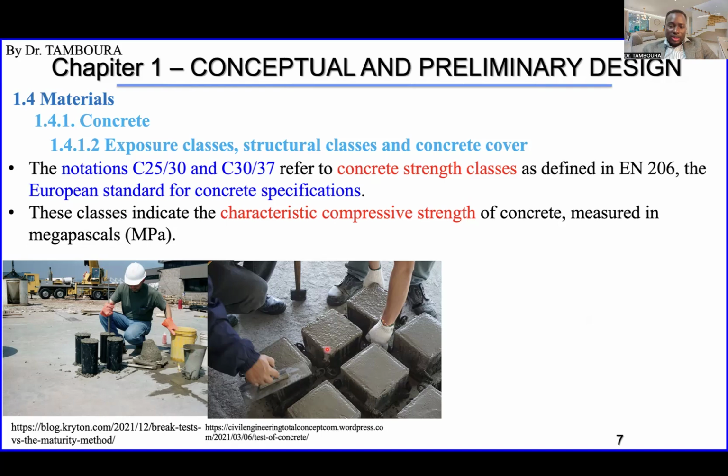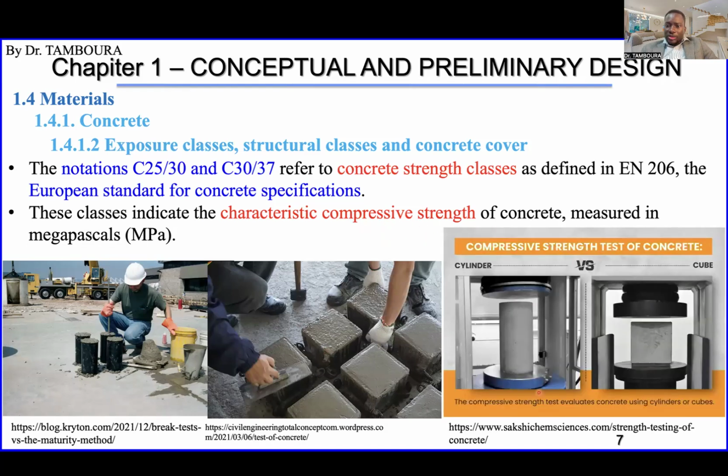Okay, and you let it dry 28 days. Okay, because 28 days is when the concrete reaches its maximum strength. And then after that, you go to test it in compression. You go to test it and find out the compressive strength of the concrete. Okay, something like this. You can see this is cylindrical sample, which is this one. Okay, and please ignore this. This is another story, something else. We will talk about this later. But I'm talking about this cylindrical shape sample, which is exactly something like this.